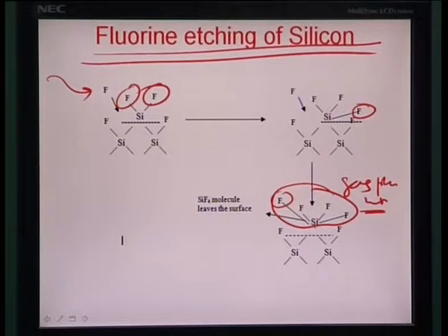Also, you have to see that all the bonds associated with silicon are satisfied. The silicon which was initially left bound in the lattice with unsatisfied bonds now has those bonds satisfied by fluorine, and it leaves as an independent entity, a gas. So, wherever silicon goes off as SiF4, you have trenches or vias created, and it is a chemical dry etching process. As the reaction happens, a gas phase is sent in, and a gas phase of silicon comes out of the process.